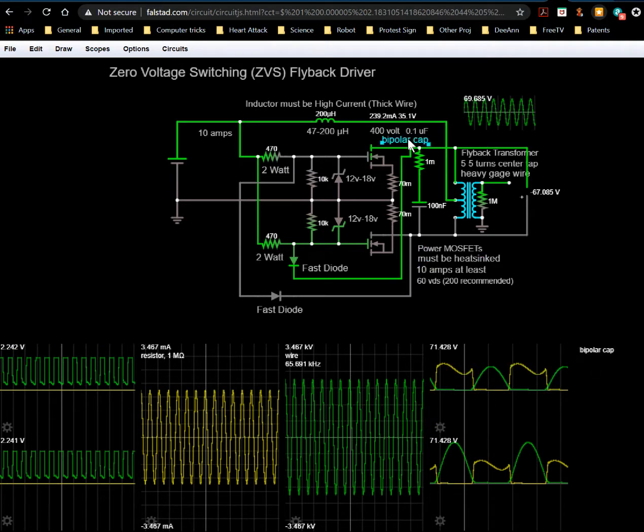But since this is a high voltage, no current flows through this diode now because it's got 68 volts here and 12 volts here. Since no current can flow through it, this doesn't siphon current away from this 10K resistor. Like it's doing here, this diode is short-circuiting this resistor, any voltage that was across it. So that's bringing the voltage down, turning our transistor off. Well, that's not happening here because this diode's off. It's not conducting. So that means this transistor's on because the diode's off.